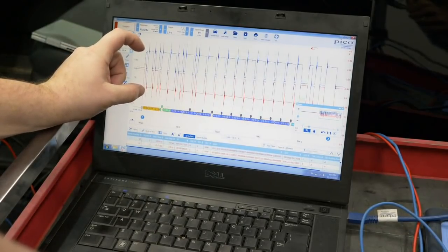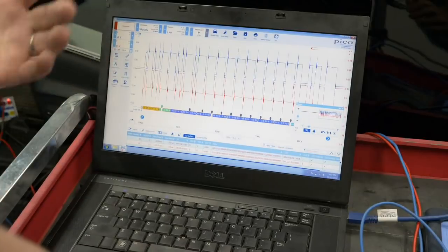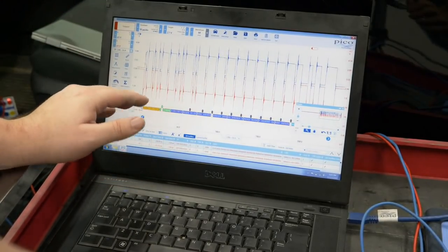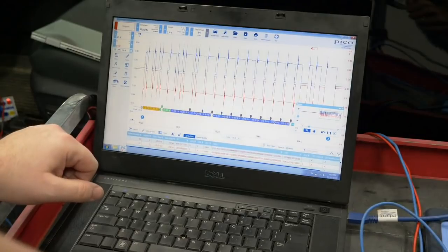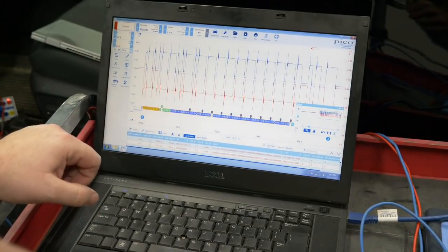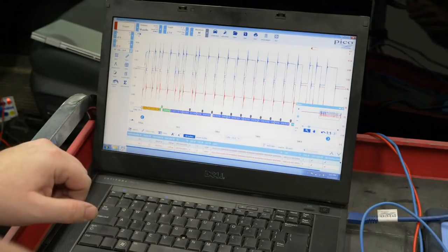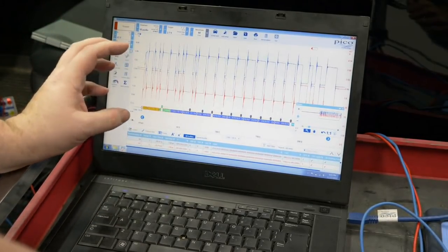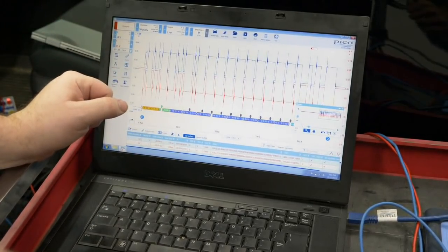If it hears someone else speak at the same time, that means it lost arbitration, and it will remain silent for whatever other device is communicating on the network. That's called packet collision. It works very differently here than in Ethernet, because in an automotive network, it's critical that messages always get across.